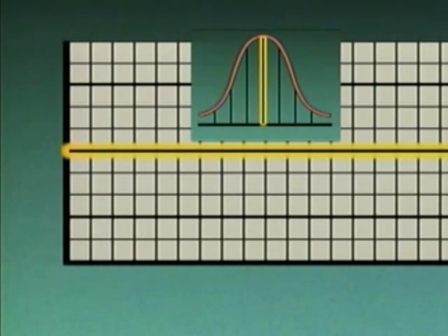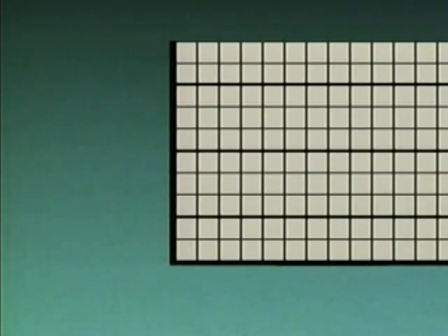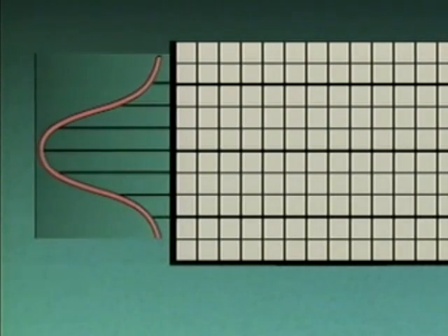Like all control charts, this one has a process center line. The center line represents the same thing that the mean value line on a normal distribution curve represents: the average value for the variation that occurs in the process under normal conditions. A normal distribution curve is typically plotted so that the mean value line is vertical, but a Shewhart control chart is plotted with the process center line horizontal. So, in order to see the relationship between a normal distribution curve and a control chart, we'll turn the normal distribution curve on its side.